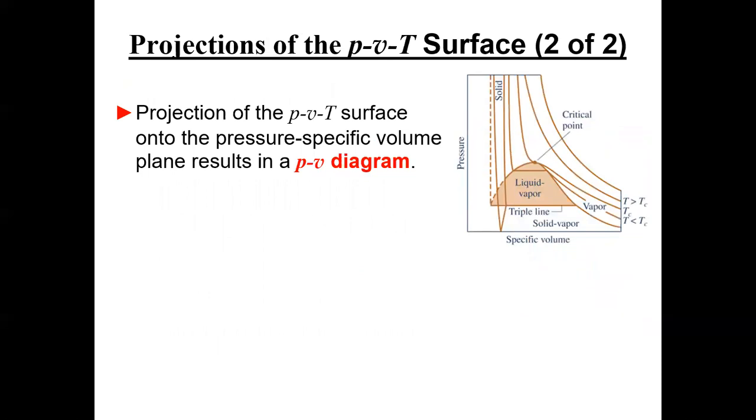So in these slides, whoever put it together, this is their PV diagram. I thought it was a little bit measly, so I put that other one in. But at any rate, there's good information here. It shows a few other things tagged down at the bottom. This indicates the triple point, or the triple line, which means on that line we can have liquid, vapor, and solid all in equilibrium with each other.